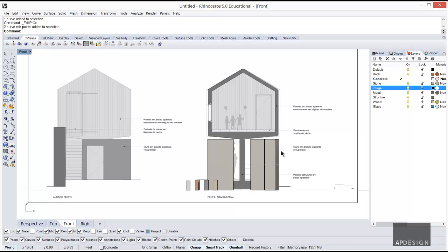In Rhino, it's a lot like any other program. When you use the marquee to select things, if you go from left to right, you have to actually contain everything that you're selecting within that rectangle. So it selected everything there. Even though it passed through this thing, it didn't grab it. Now if I go the other direction, it'll be anything that passes through that marquee. So now I passed through that, so it's going to grab that.